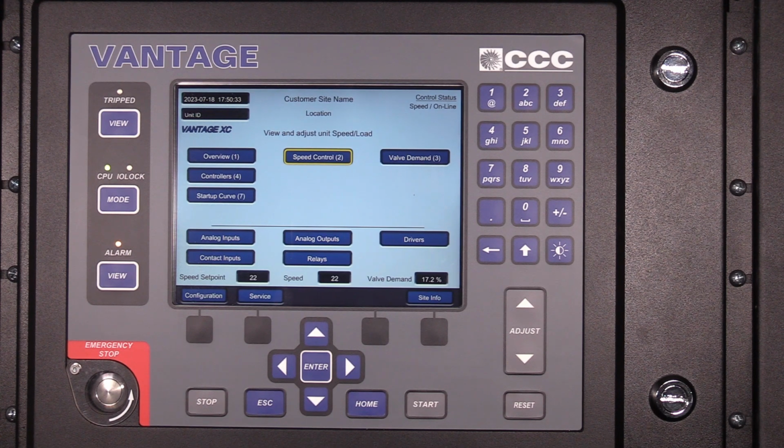The Speed PID Optimizer routine will automatically calculate your system dynamics and provide the following benefits: improved system response to disturbances, tighter control at the set point, and improved system diagnostics. We will first overview the optimization test sequence.